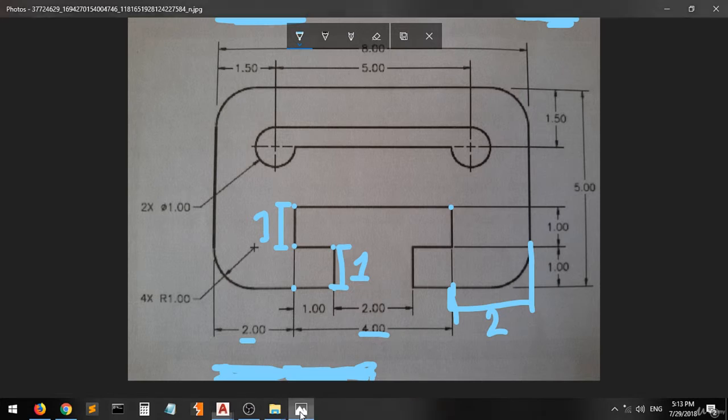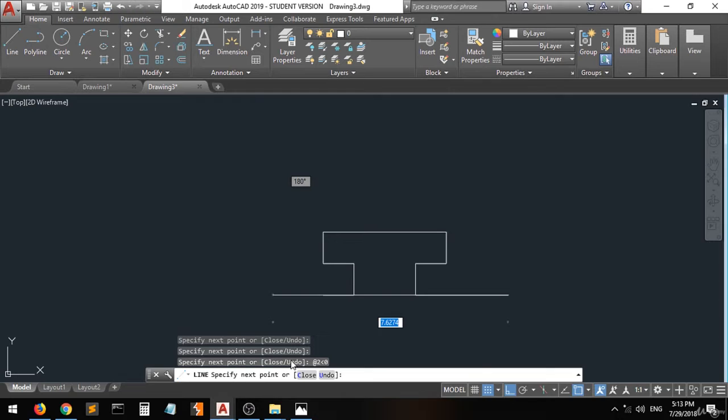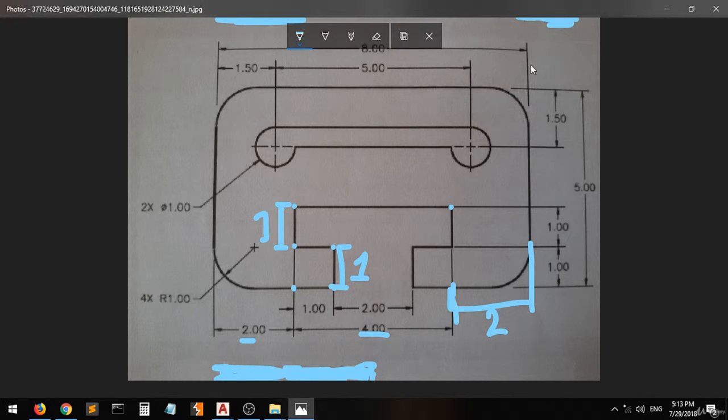Excellent. Now, going back to the drawing, we will move this whole distance, which is 5. As we said, we will create it with pointed corners, then we'll create the fillet shape. Don't forget this: we'll create it as a simple rectangle, then we'll do the fillets. Now, we'll move up at 5 in the direction of 90, enter.